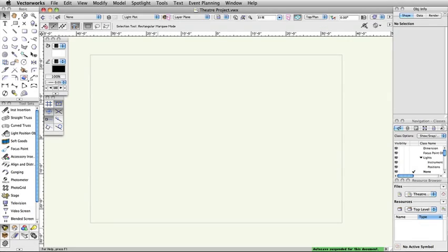There are 2D locus and 3D locus tools located in the basic palette and 3D modeling toolset respectively. Locus points and datum provide guides for drawing and reference points as needed. You can also convert locus points and other objects into guides. This will move the objects into a guides class, modify the attributes of the objects, and lock them in place.